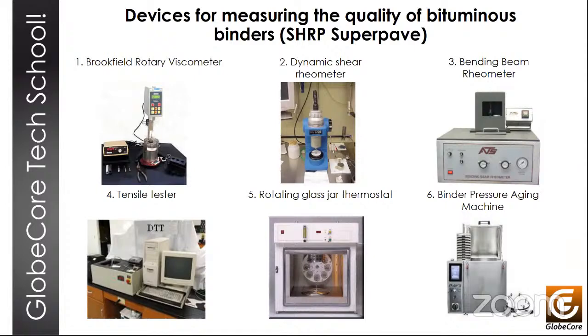So the SuperPave system that we've discussed does have both advantages and disadvantages. And the advantages are the application of fundamental physical and mechanical characteristics of the binder. It's the uniformity of requirements for the various types of binder. It's the relationship between the requirements and the actual operating conditions of the road layers.